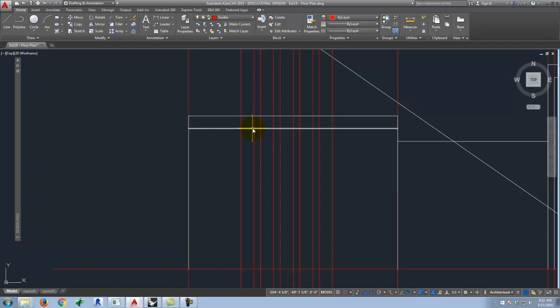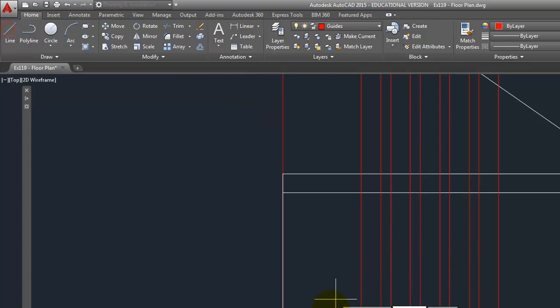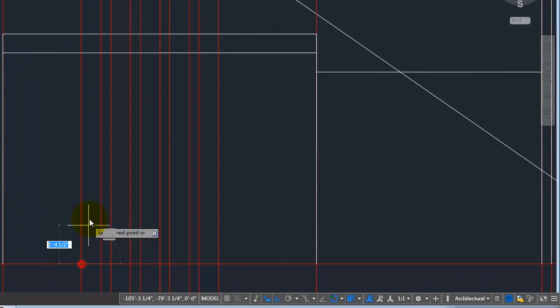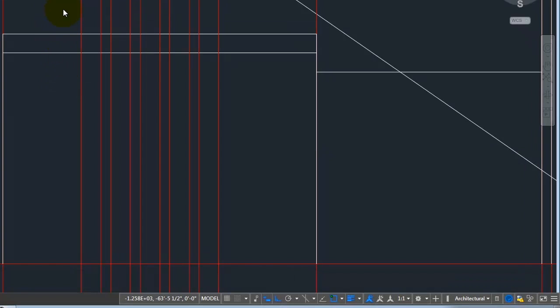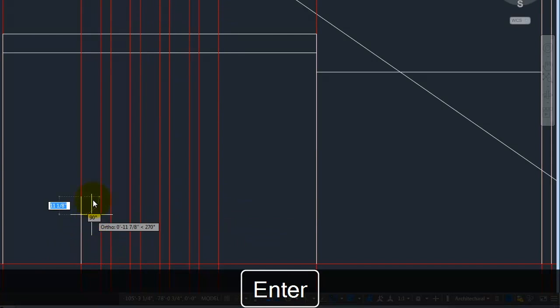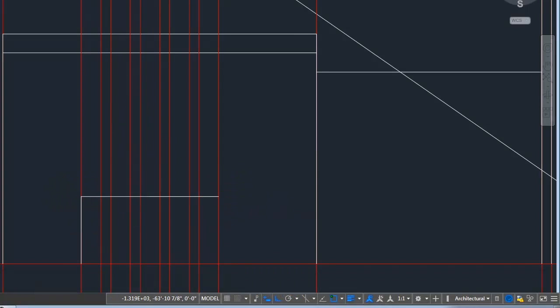We know where the tops of the windows are going to be right there, but I don't know where the bottoms are just yet because I need to create the bottom. So I said it would be maybe 42 inches up from the bottom. And so let me just go ahead and draw. Let me switch my layer here to be on the south elevation. Somehow south elevation doesn't jump out to me here. And go up 42 inches, and we'll just draw across. So I'm using that just kind of as a general guide, and then I can come back with the rectangle tool here, and I can draw each of these windows.